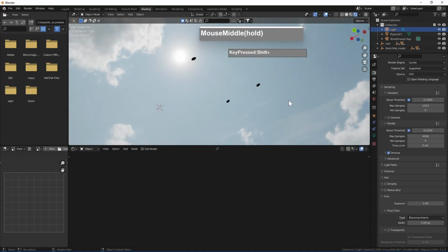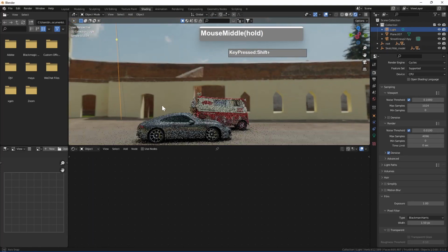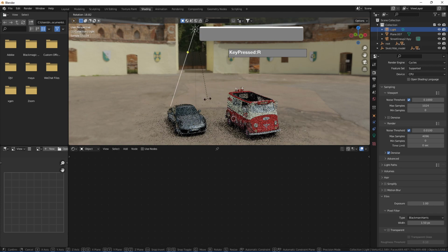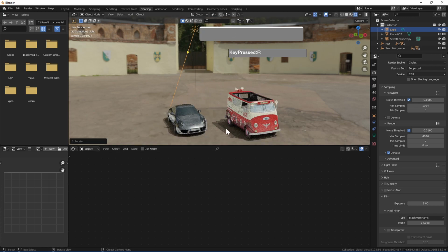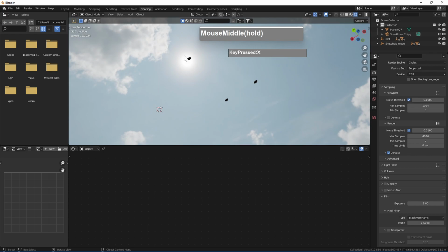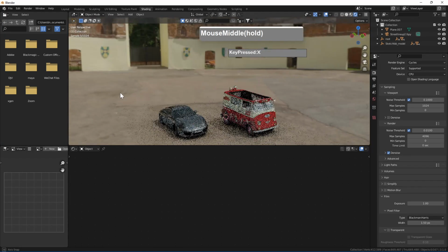It's because the sun in this picture is actually casting an additional shadow, and our additional light over here is also casting another shadow. For example, I can rotate this, and you can see that there are two shadows over here. Now, if you're using the HDR and you feel that the HDR light is sufficient, you can actually get rid of this light. For this example, I'm going to delete this light by pressing X and then delete. And now the only light source is basically in this picture here. The sun is actually lighting up my scene.